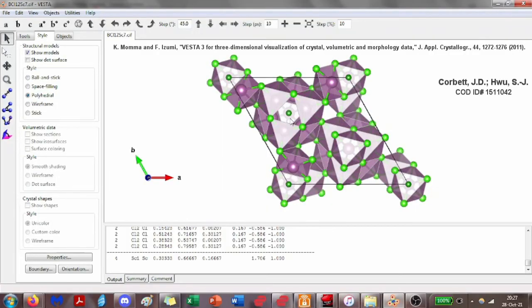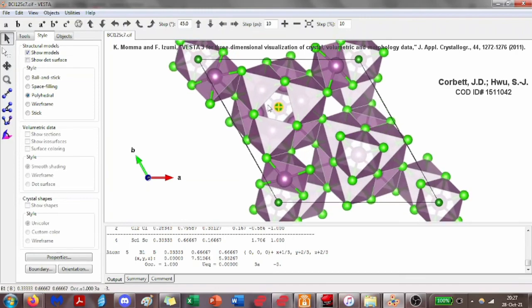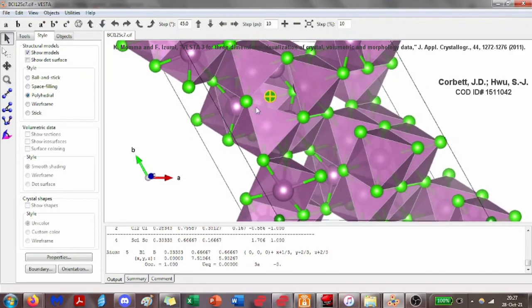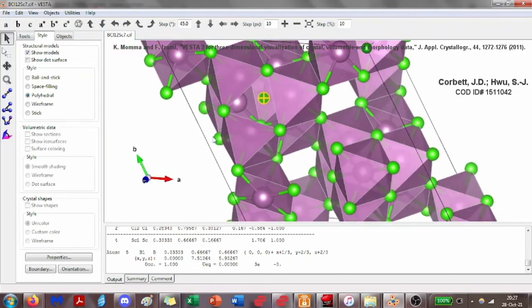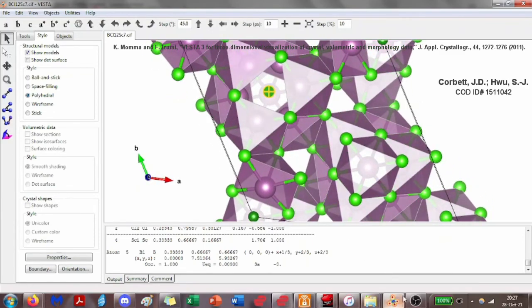Next, interstitial defects are defects in the crystal structure where a small atom has managed to squeeze in between the larger atoms making up the rest of the structure. It can be a bit difficult to demonstrate a single interstitial defect with bubbles, so here's a model using the Vesta software, showing a small atom wedged in between the normal atomic sites.